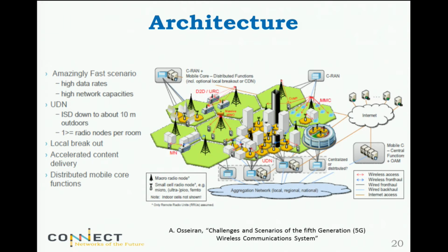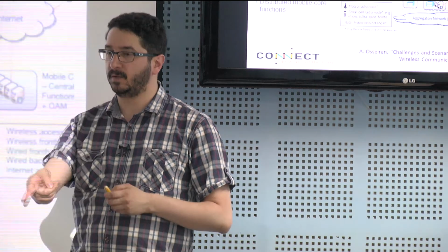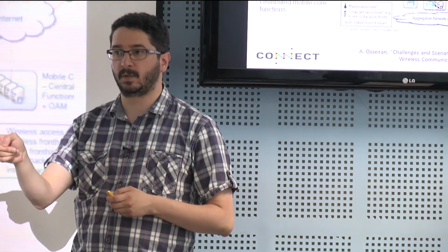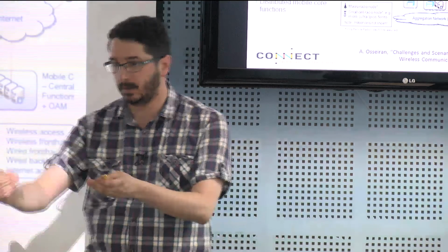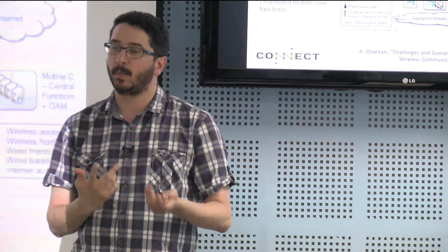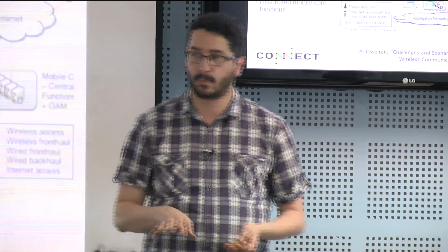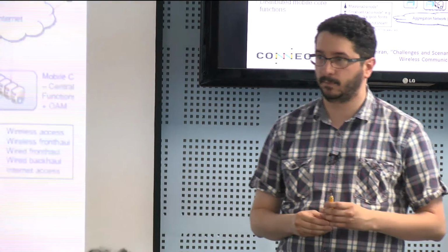Possibly, especially if you go into the millimeter wave domain, I think you can use a lot of the benefits of massive MIMO. So if I transmit very directionally, most likely I won't interfere with you, unless you're really unlucky and your user is along the same line. Probabilistically that won't happen, right? So there are a few things you can do, but you're right, it's a problem. Okay, so it has to be taken care of.